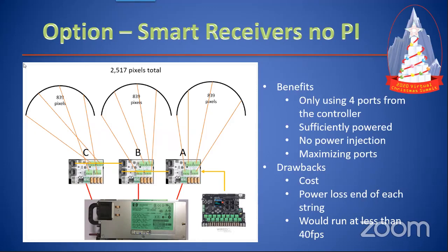Let's see. So 100 pixels per port. You can run more either at lower brightness or power injection. I think what we're saying is, again, you're limited by what's the draw for each port, right? Correct. That's your limitation, is the draw on the ports.